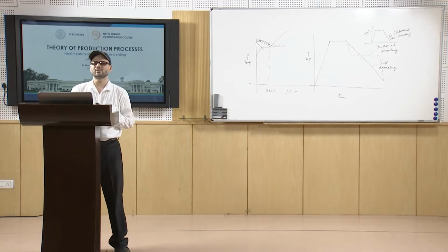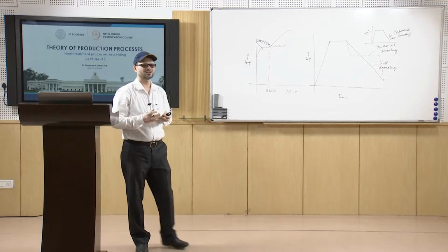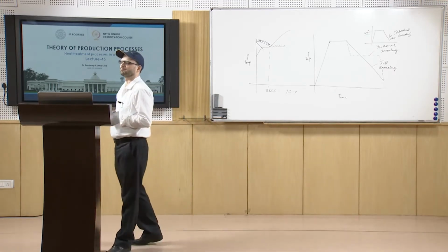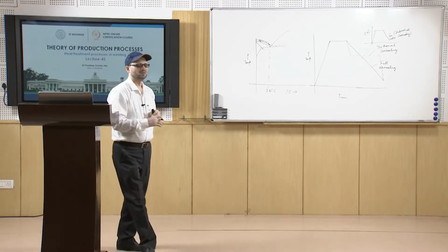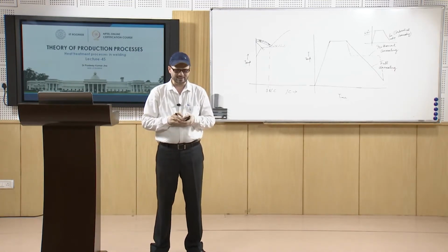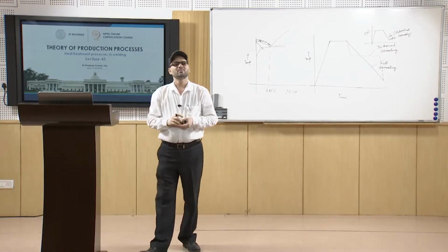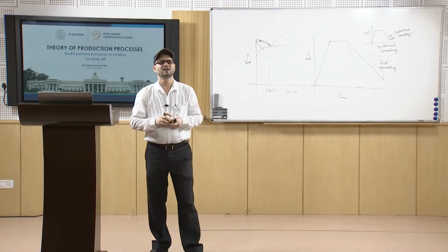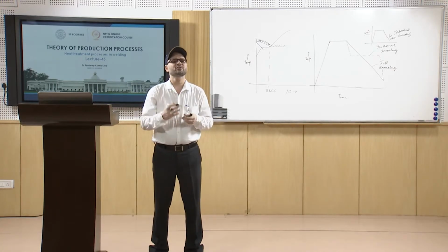Depending upon the cooling rate, you will have different structures, and martensitic structures are quite common when we go for quench hardening of the material. This way you do the quenching. The strength is increased, but ductility is decreased. Many times we get the martensitic structure, which is quite hard and extremely brittle, so we need to go for the tempering treatment.